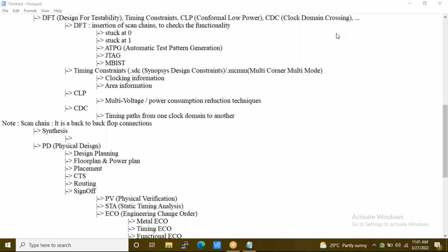Again, what do you do when you are jumping down from the bus? You walk for some time on the ground, then you leave the bus handle. Same thing: if you don't use synchronizers between one domain and the other, there is a very good chance that it will lead to metastability. Metastability means unknown condition. Unknown condition means X. Then our complete chip will go into an unknown condition.